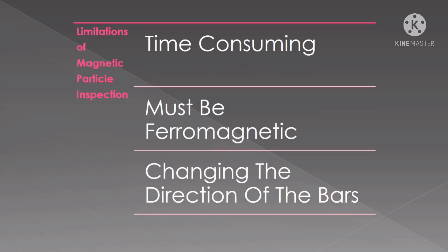First, the inspection method can be quite time consuming depending on the quantity, configuration, and other features of the part or component to be inspected. One reason for this is the need for inspecting in two 90-degree opposing directions. This is to ensure discontinuities are detected regardless of the component's orientation. Some personnel still forget this and take the shortcut, which results in inaccurate detection.